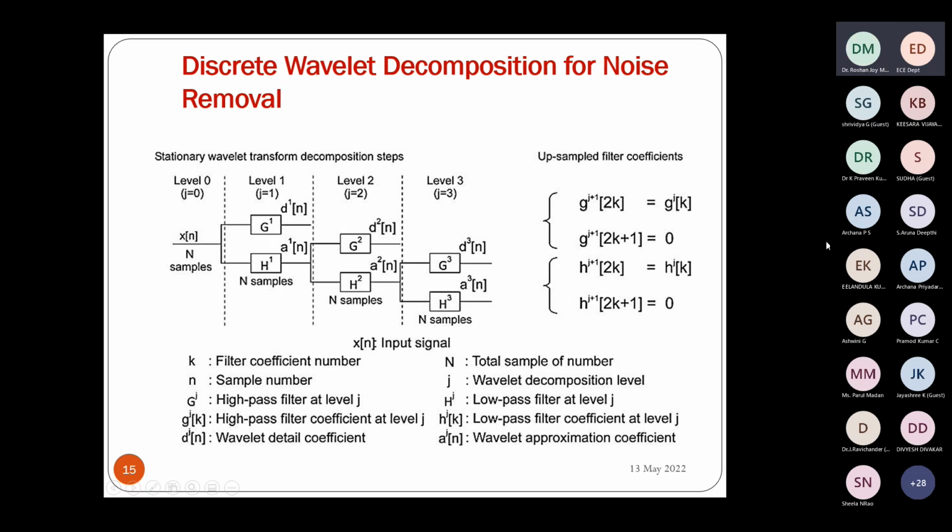So this process has to be continued. The original signal is decomposed into G and H. Then again, H is decomposed into another two subbands, and that process is continued. So this subband decomposition continues. You can continue it to any depth. At level 0, you have the original signal. At level 1, you have the low pass and high pass filters, which are further decomposed, and it continues.